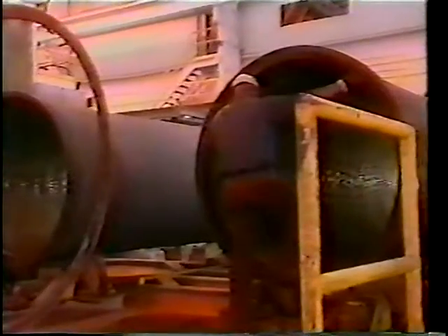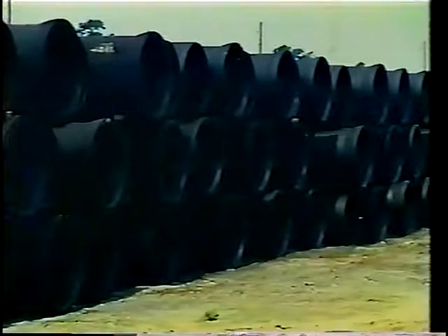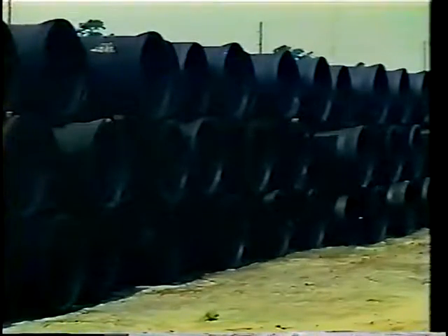Ductile iron pipe are centrifugally cast and then furnace annealed to provide the required properties. They are used for non-pressure and pressure applications. Ductile iron pipe are generally furnished with an asphaltic exterior coating and cement mortar linings. Polyethylene encasement can be used in aggressive environments. Bonded coatings can also be applied.